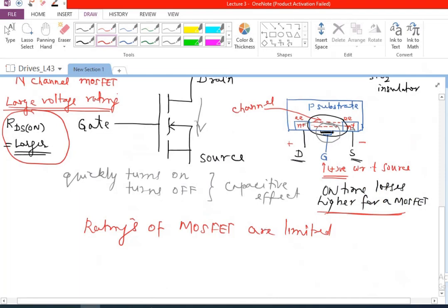So you should read the data sheet before you select a particular device for your circuit, because you should be able to, first of all, design your circuit. You should be able to see the simulation by looking at what is the maximum current at each of the nodes, how much is the device current that is being carried in the circuit, and accordingly, you will choose your devices when you are actually making the circuit in the hardware, finally.